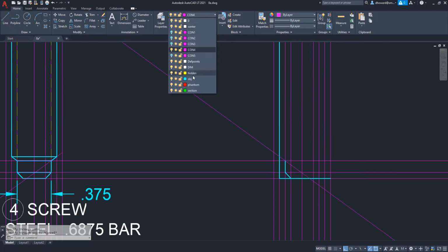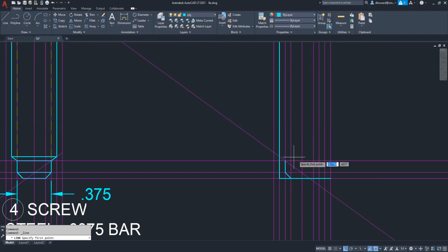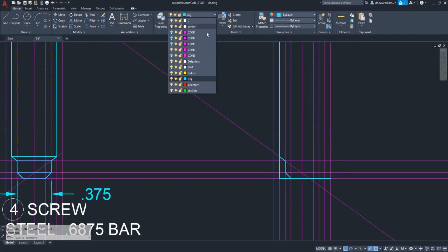Okay. And then follow that guy up to there. So this is a 1/16 inch chamfer on the here, and we have this 3/8 diameter here, and then our outer diameter is 1/2 inch. So let's trim that stuff off and then mirror it.